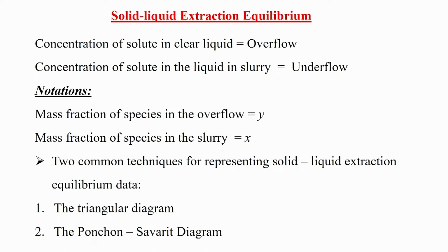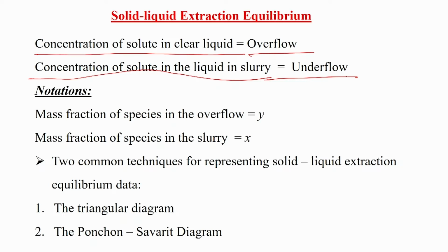Here we will be discussing the concentration of the solute in the clear liquid, the overflow, which is equivalent to the extract in the liquid-liquid extraction process. Then the concentration of the solute in the liquid in the slurry, or in the inert material or in the cake, is termed the underflow.